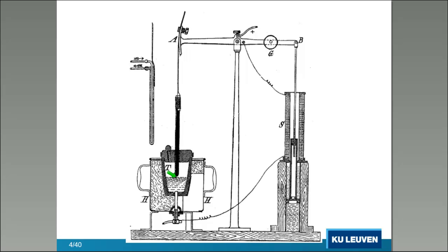That means ionization of air and the conduction of electrical current coming from the source here on the left of the picture over the connectors here and over the electrode, which is in graphite. Here, the conduction continues not by conducting material, but just by air, by ionized air. This we call an arc.